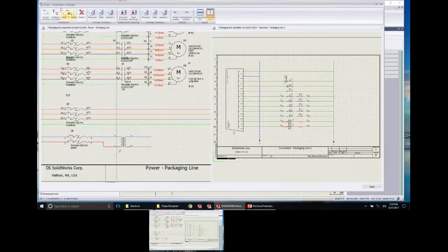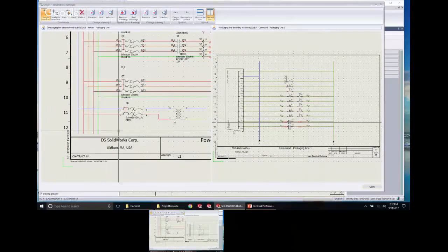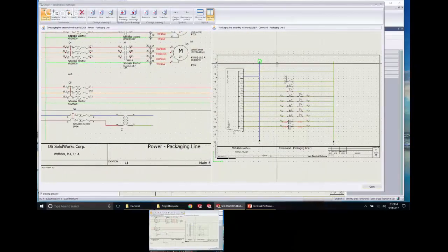So we're going to use a single insertion right here. When I do a single insertion, and I move down to these drawings, I can actually change the drawings too using these commands. But when I go to the single insertion, you see any open wire that just terminates to nothing is green.